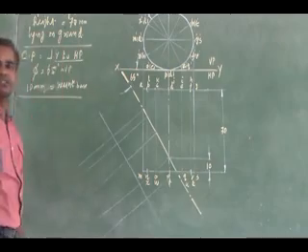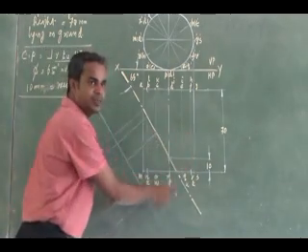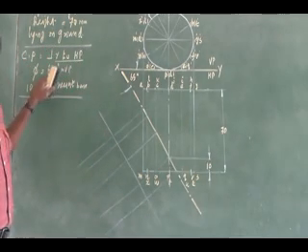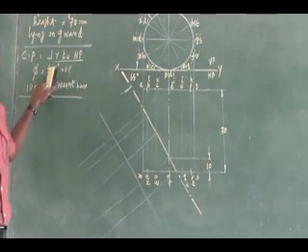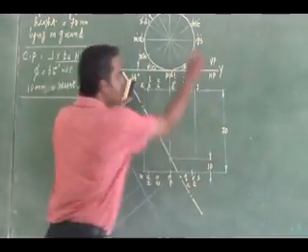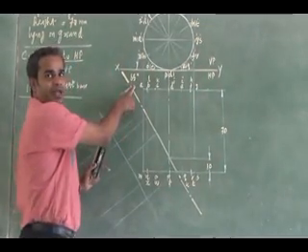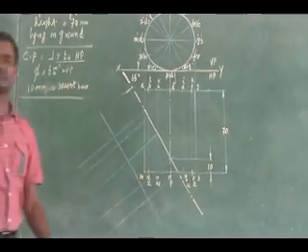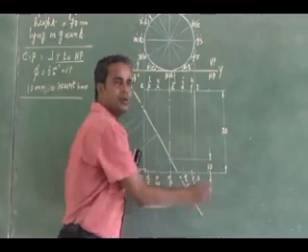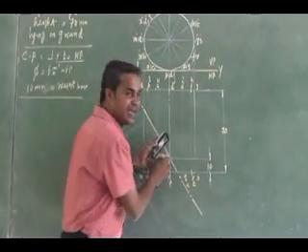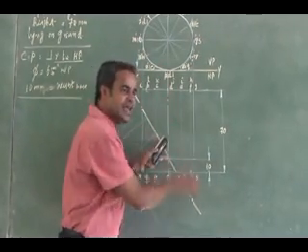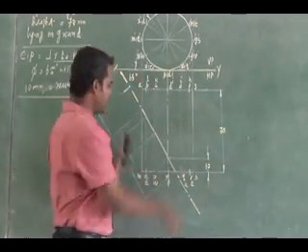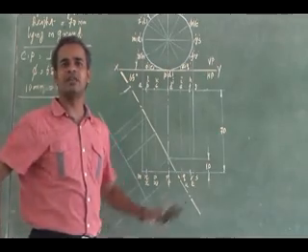So I have to represent the cutting plane on HP, that is on top view. So I am representing the cutting plane on top view. And the orientation is given 65 degree. So it is 65 degree inclined to VP. Then it is 10 mm from the nearest base. The nearest base is MN base. From there it is 10 mm. It is meeting the axis at that location. And it is 65 degree inclined. So I have represented my cutting plane in the top view.